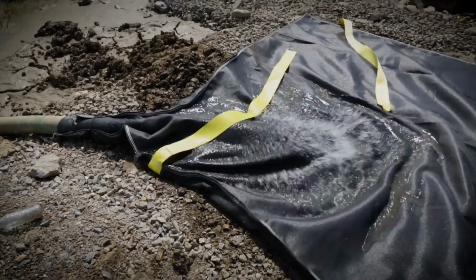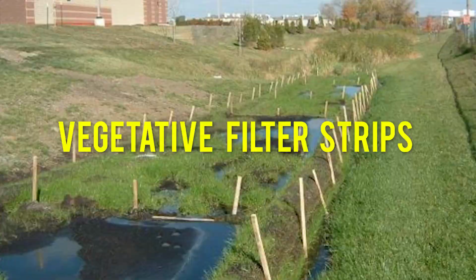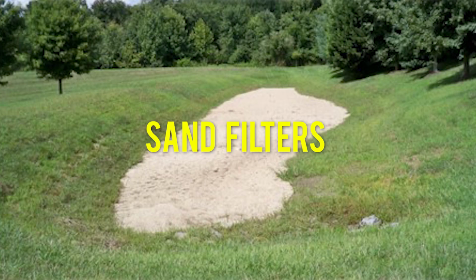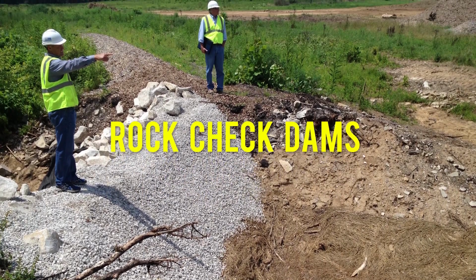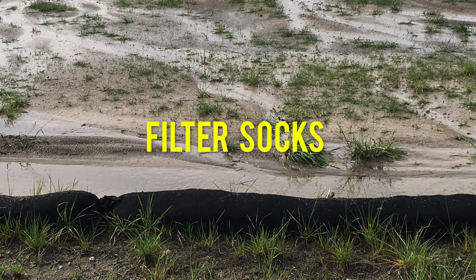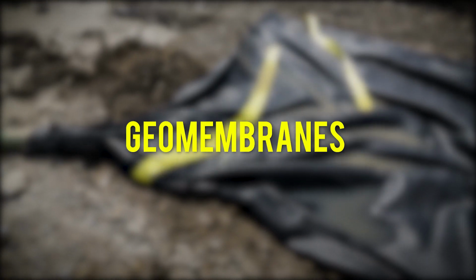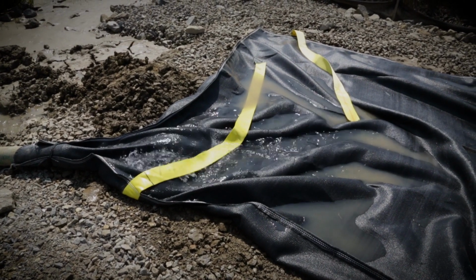Control of discharge water and waterborne sediments may be accomplished with vegetated filter strips, dewatering bags, flocculants, sand filters, rock splash pads, skimmers, rock check dams, rock filter berms, turbidity barriers, silt fences, filter socks, erosion control blankets, geotextiles, geomembranes, or other means to control erosion and the release of sediment beyond the construction limits.